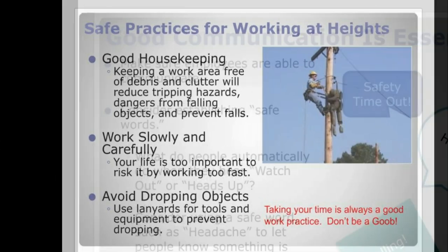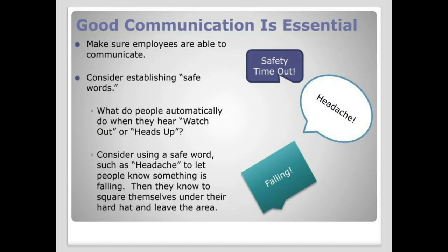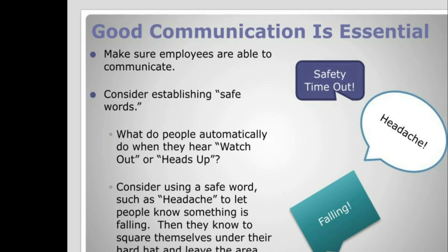Don't be a goob. Good communication is essential. Make sure employees are able to communicate. Consider establishing safe words. What do people automatically do when they hear "watch out" or "heads up"? Consider using a safe word such as "headache" to let people know something is falling. Then they know to square themselves under their hard hat and leave the area.